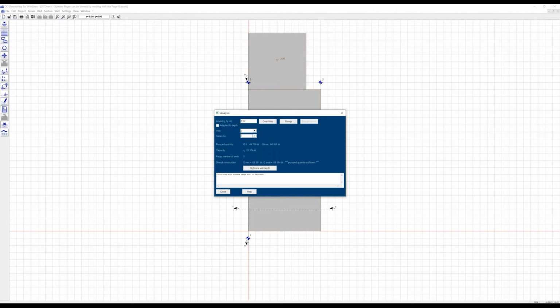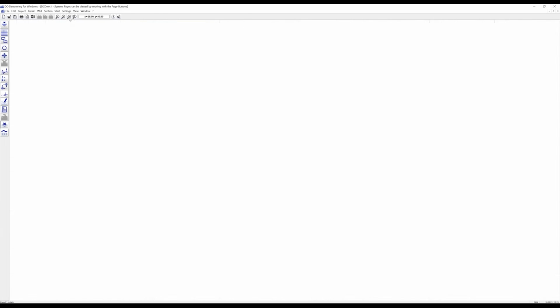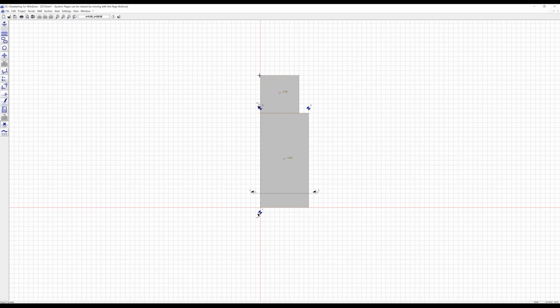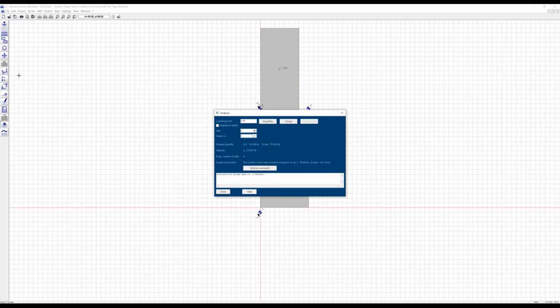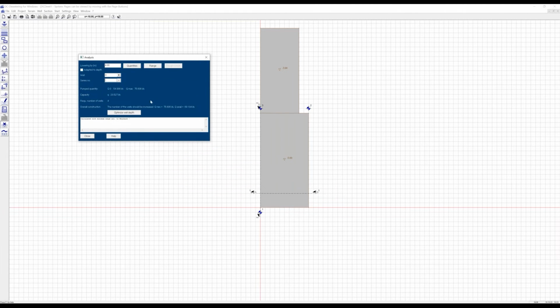that is still sufficient. Okay, I wanted to show you an example where it's not sufficient. We can use a larger area here. So just dragging the points. And in this case, as we have a larger area, our available capacity is not sufficient compared to the required capacity. But this is calculated for a lowering by 4 meters, because at this point here, we want to go to 5.50 meters. We won't need this depth for the second area here, because with a depth of 3 meters, it would be sufficient to go to 3.50 meters.